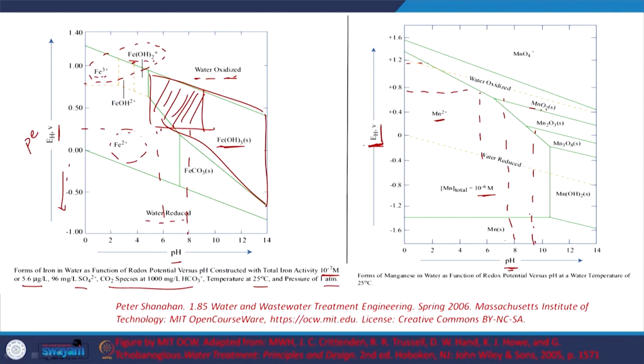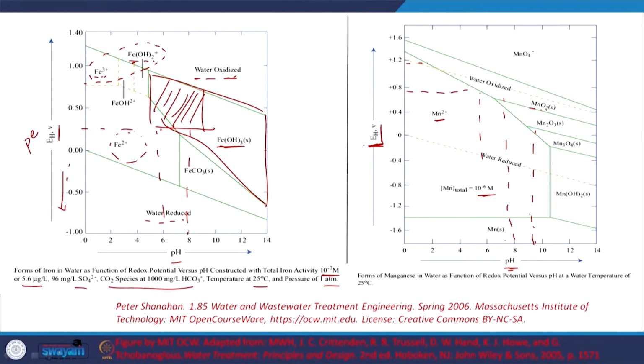In groundwater, where there is no oxygen, typically reducing conditions prevail, that is why Fe2+ and Mn2+ are abundant. But out here above the surface, where oxygen, which is an oxidizing agent, is aplenty, you are going to have oxidizing conditions prevailing, and thus the oxidized forms are going to prevail. In general, at neutral pH, if oxidizing conditions prevail, Fe2+ and Mn2+ precipitate out as Fe(OH)3 or MnO2. So, that is something to keep in mind.